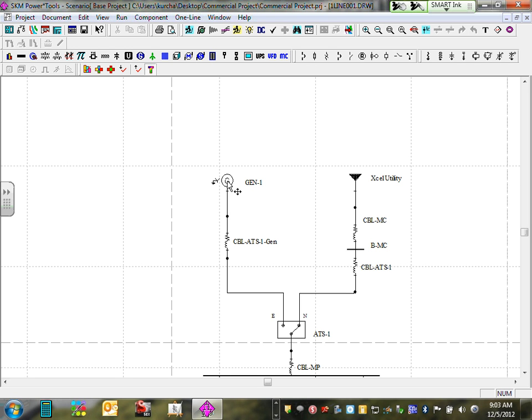I can give you a very simple story. One time I did short circuit analysis, Jeff, for one of my projects, and I put 20, what's supposed to be, I think like 100 feet. I didn't look on the side, it was 100 mile. What a difference between 100 feet and 100 mile for transmission lines. The software took the mile.